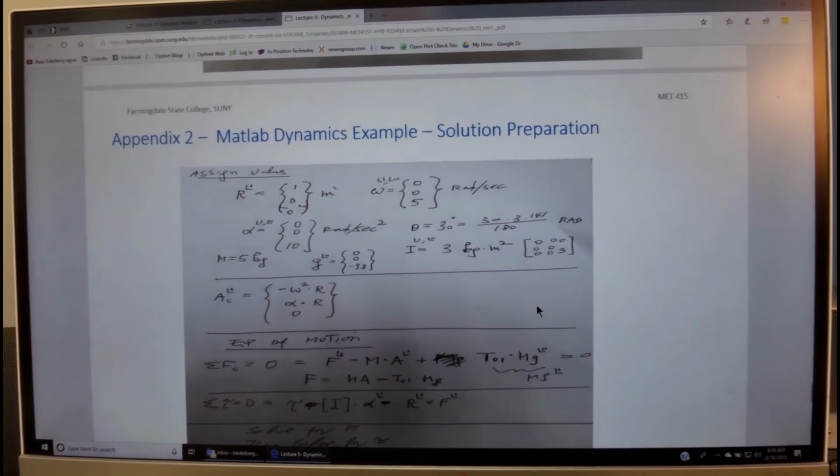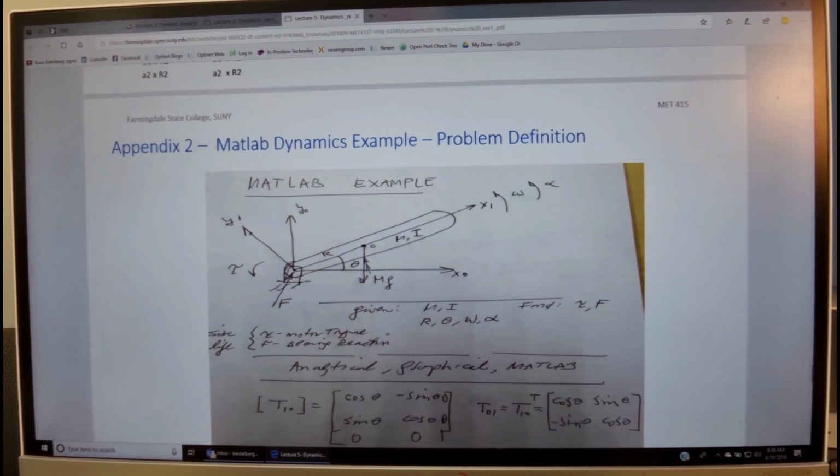So in this example, we see that the centrifugal acceleration is from this point towards the center of rotation. It's mass times this acceleration. This acceleration is this lever arm times omega squared, because it's two-dimensional, and the tangential acceleration will be in this direction, and this is this vector arm times the angular acceleration, and then we have the force of gravity in this direction.